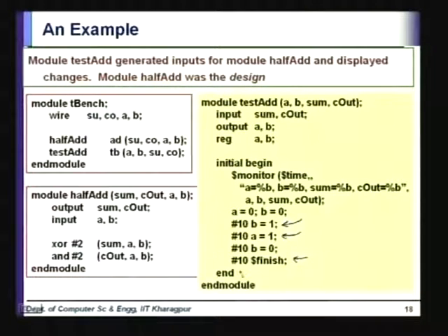Alright. Why do we have this 10 here? It is allowing the output to change for certain. Right. So this is allowing the delay required for the last simulation step. When you are doing this with B equal to 0, A equal to 1, for that you need some time for the output to settle. Why? Because these gates have some inertial delay. So you have to wait until these gates settle, right.